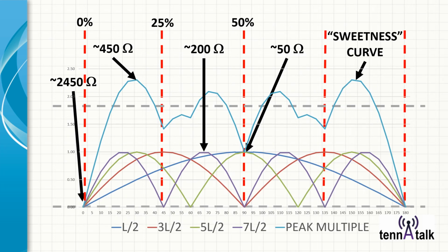So now, let's take a look at a half wave at 40 meters. This is a plot of the current along a half wavelength of 40 meters. That's the blue line here. And notice that if we switch up from 40 meters to 20 meters on that same length of wire, we get the red lines. And if we switch up to 15 meters, we get the green lines, these green humps in current. And finally, at 10 meters, we've got the purple line, which are these humps here.